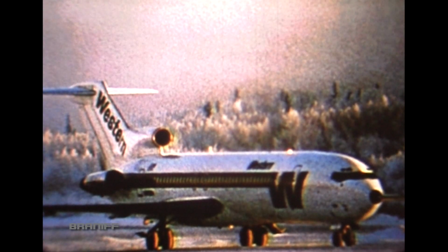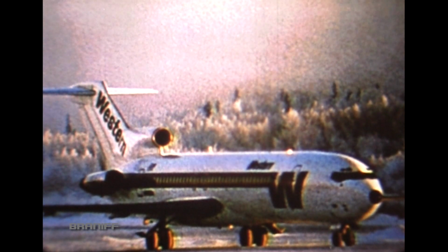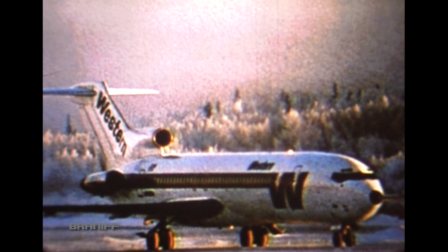Before moving into takeoff position, make a final check to verify the airplane is still free of snow and ice. Never assume that snow will blow off the wings during the takeoff roll. If not completely certain the airplane is free of snow and ice, return to the gate. Prior to takeoff, make a static engine run-up. Check for normal engine indications and smooth operation.